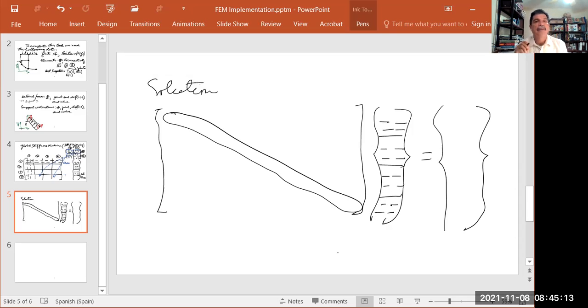And then you need to select one of these. So you have to multiply the number of the joint minus 1 times 3. That's this position. And then you have to add the position or the degree of freedom that you have to identify. In this case, this is 10. So this is the element that we need to be worried about. Let's call it big K, LL. And we know that this is 10, this is 10. So that's the position that we know.